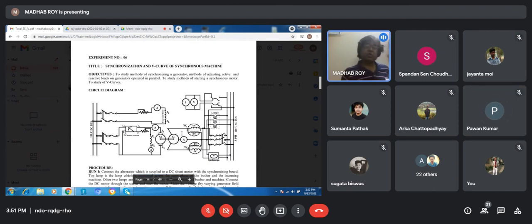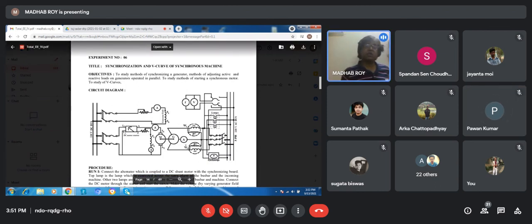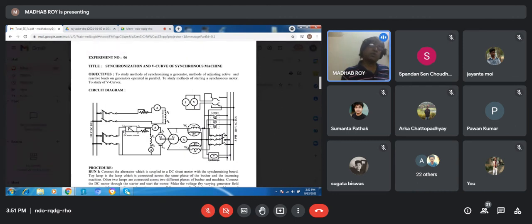So now if this motor is this synchronous machine, you have to now stress on the construction of the synchronous machine. You don't know what is the type of the synchronous machine. Synchronous machines are of two types: one is called cylindrical rotor, another is called the salient rotor type. In the cylindrical rotor machine, the D-axis and Q-axis reluctance are equal. But in case of the salient pole machine, you will have a difference of reluctance. The direct axis reluctance is very low, whereas the quadrature axis or Q-axis reluctance is very high. So due to this difference in reluctance, it will run as a reluctance motor. Got my point? Yes, sir.